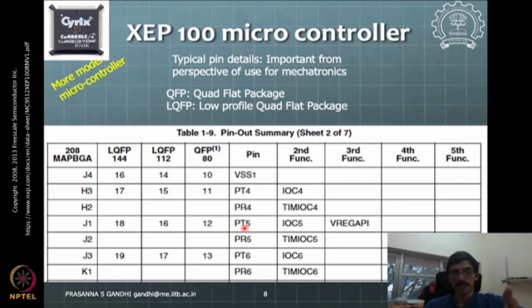That is a possibility in the new modern microcontrollers. With older microcontrollers, there will be no such flexible pin functionality. A GPIO pin will do only digital input output; there is no other function that pin can do. But now these modern microcontrollers have the possibility of pins having multiple functions, and depending upon the package, there are different kinds of packages.